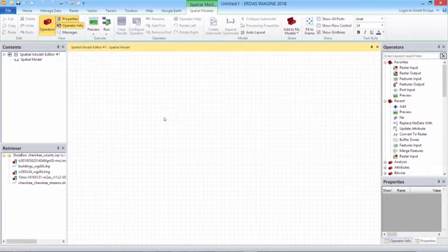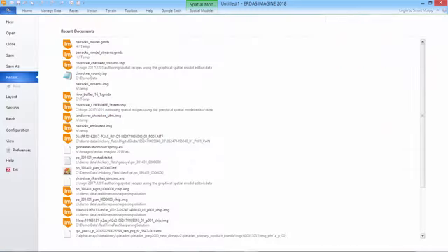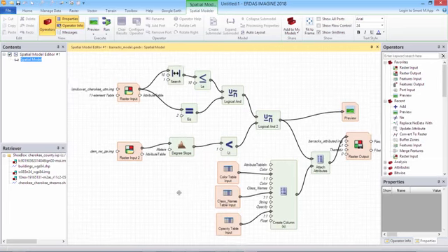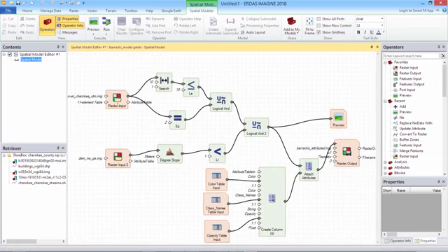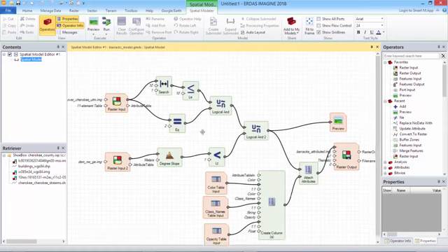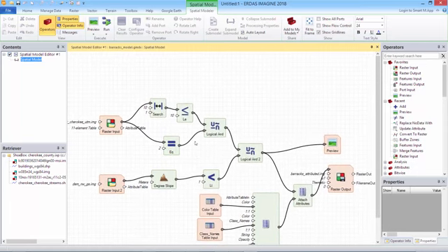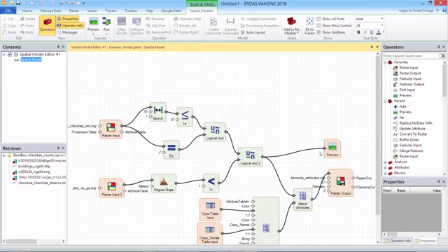And what I'm going to do is open the model that we prepared earlier in previous e-training modules, just to show you what we have so far, basically bringing in a land cover classification to look at the water extent from the land cover, and also DEM for looking at the slope, and also the forest canopy from the land cover classification. As I say, that might not be as accurate as we want it to be, so we're going to bring in that streams dataset as well and buffer that by the similar 150 meter distance.